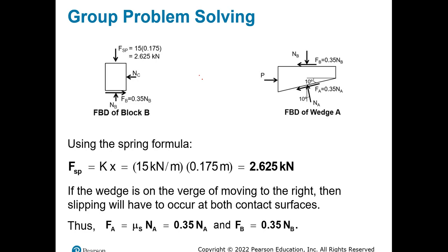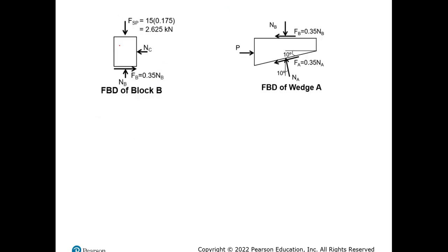So just by looking at these equations or these free body diagrams, I need to make a decision. I know that I need to calculate the normal in B and the normal in A. If I look at this one right here, I have normal B, normal A, and I have P. I wouldn't go with A. But when I look at this one right here, I have NC, of course, and I have NB, and I have other things. But what is very important is that with a simple sum of forces in the y direction, you can find the value of NB, because you have this one and only this one in both. So therefore, if I do sum of forces in the y direction, I don't need to do anything else.